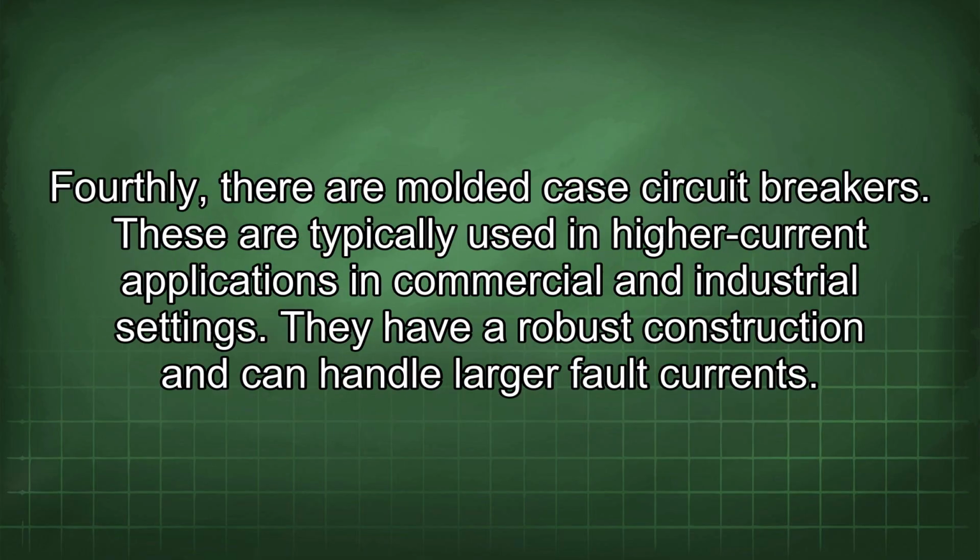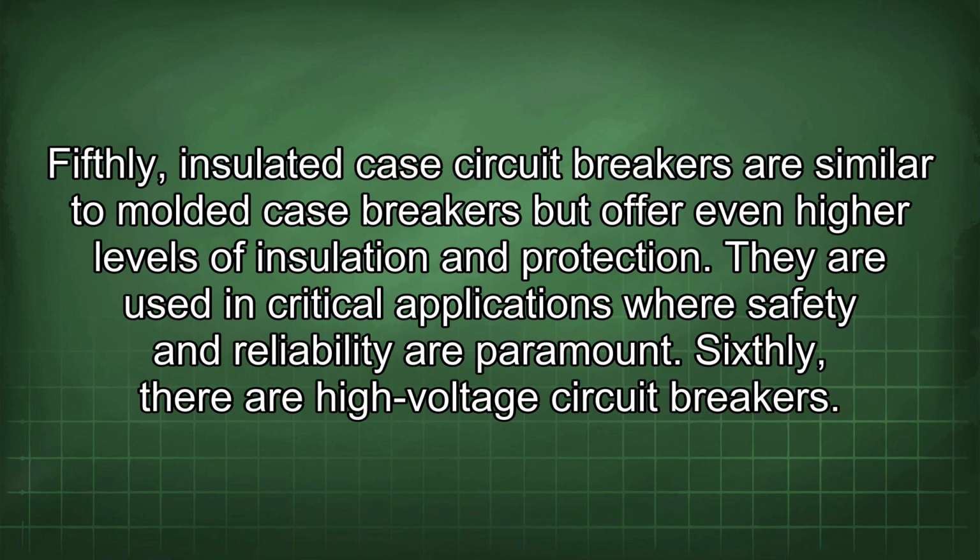Fourthly, there are molded case circuit breakers. These are typically used in higher current applications in commercial and industrial settings. They have a robust construction and can handle larger fault current. Fifthly, insulated case circuit breakers are similar to molded case breakers but offer even higher levels of insulation and protection. They are used in critical applications where safety and reliability are paramount.